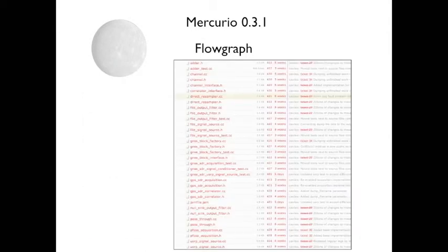GNSS blocks are what the design considers modules. These blocks are an aggregation of GNU Radio blocks that form a specific flow graph. GNSS blocks encapsulate the way GNU Radio blocks are instantiated, connected, or configured. This way the flow graph can interact using GNSS blocks and the configuration system.